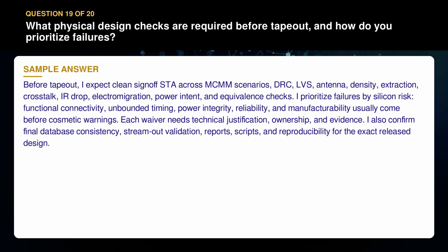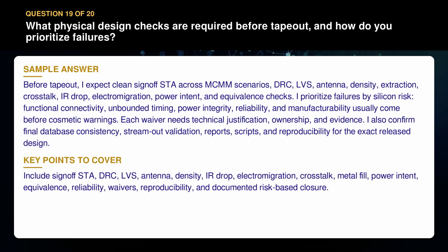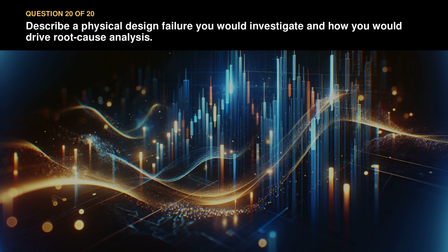I also confirm final database consistency, stream out validation, reports, scripts, and reproducibility for the exact released design. Include signoff STA, DRC, LVS, antenna, density, IR drop, electromigration, crosstalk, metal fill, power intent, equivalence, reliability, waivers, reproducibility, and documented risk-based closure.